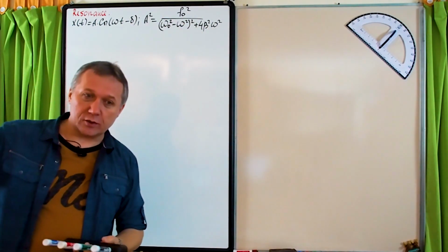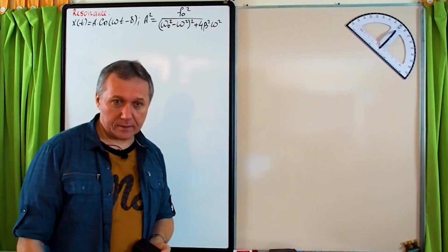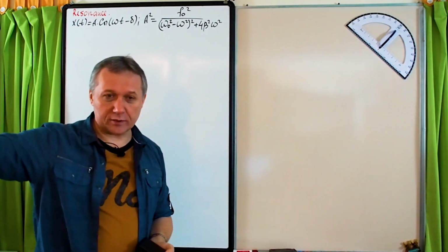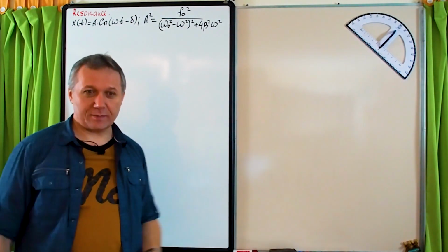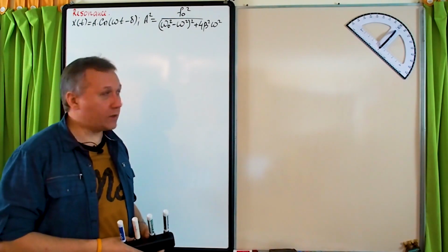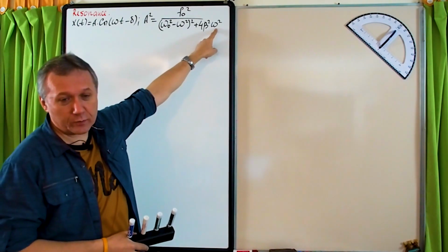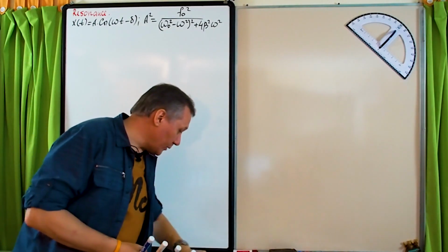So we sit and tune the frequency of our driving force. Let's assume it's tunable, and we tune it from 0 to infinity in a search for a maximum point, the frequency at which the response of the system, the amplitude of the system, is maximum, and we solved that problem.